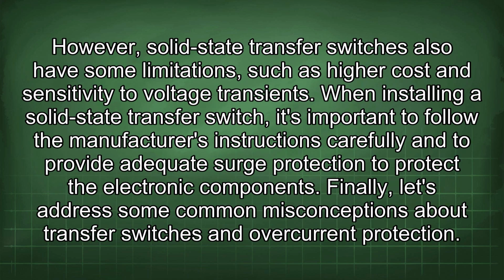However, they also have some limitations, such as higher cost and sensitivity to voltage transients. When installing a solid-state transfer switch, it's important to follow the manufacturer's instructions carefully and to provide adequate surge protection to protect the electronic components.